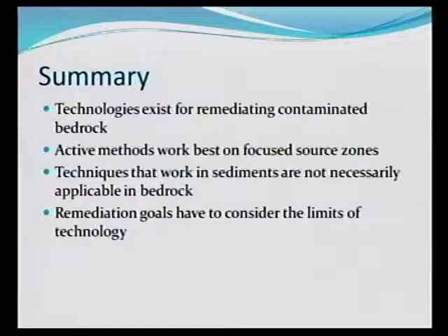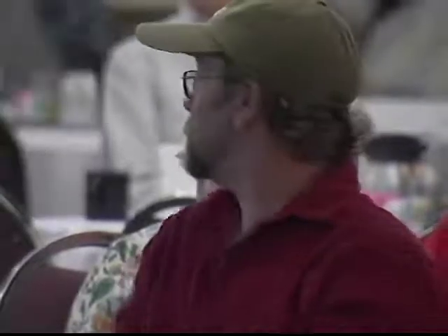And so when you see remediation technologies that are touted as, oh, this is amazing, it cleaned up the plume in 2 days, you have to ask yourself, well, is that going to work in my system? Just because it worked in a nice glacial aquifer doesn't mean it's going to work in bedrock. And so the remediation goals, unfortunately, have to consider all those things. We go back to the cube. You have to consider what's your goal, what technologies are going to work, and what challenges are presented by the geology and the hydrogeology.